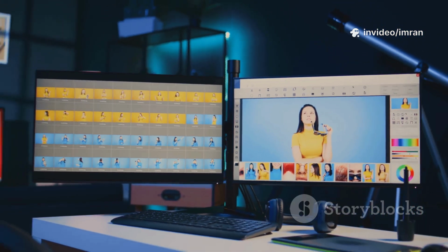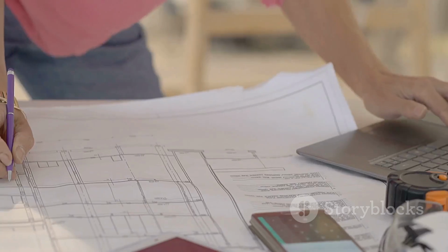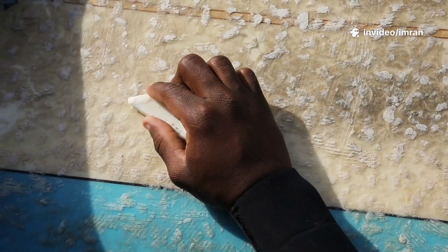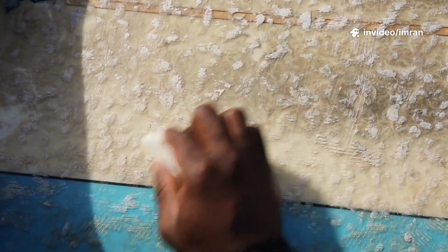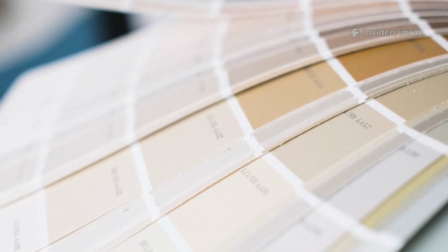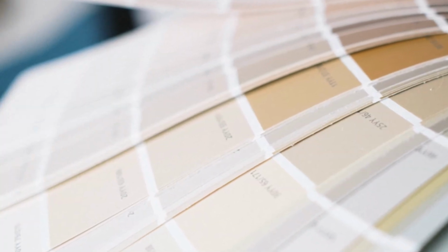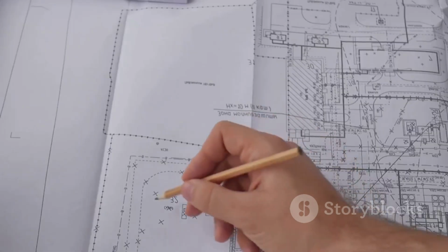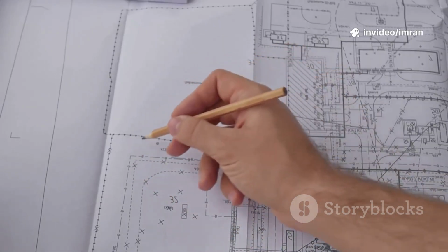To draw on a layer, you need to set a layer current. In the Layers panel, use the drop-down list to select the layer you want to use. Any new object will be placed on the current layer and inherit its properties. To move an object drawn on the wrong layer, select the object. Then, use the layer drop-down to select the correct destination layer. This is the fundamental workflow for organized drafting. Always check which layer is current before drawing a new object to save time later.